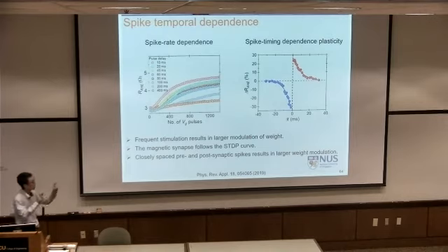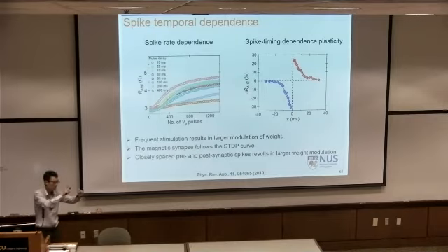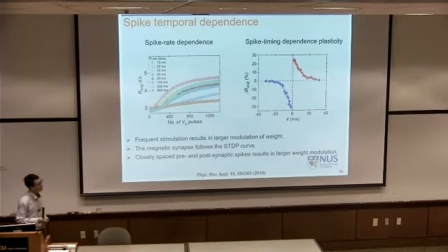The other one is you can give 2 pulses into the device. If those 2 pulses are nearby, basically you have a higher correlation, then you can change the potential by a large magnitude. If 2 pulses are far away, basically no correlation, and then you have little effect. So this is called spike time dependent plasticity, which is an essential feature we have to show if this is a neuromorphic device. So indeed, it shows our device can mimic this synaptic function, mimicking our human synapse.